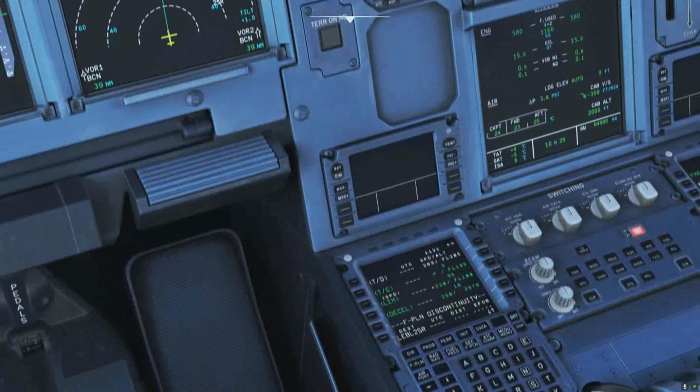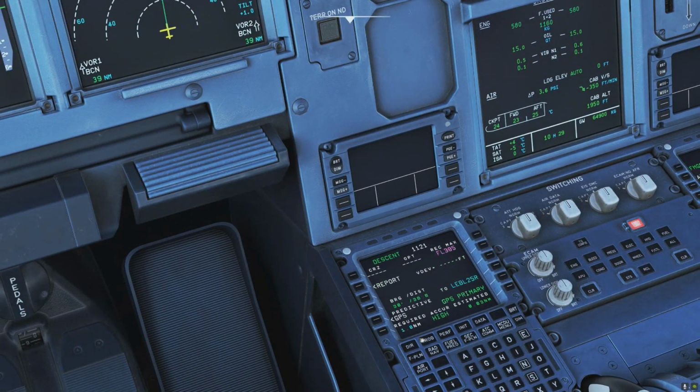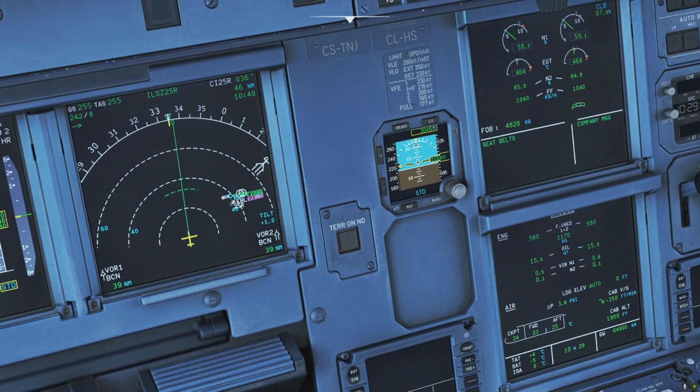And in terms of distance, if you look here, this distance now makes no sense whatsoever, because it tells us we are 38 miles away from the runway, but this is measuring from the aircraft directly to the threshold. This is not what we'll be flying. So in terms of distance, what you can calculate is that you're going to be flying 10 miles outbound and 10 miles back inbound. That is usually what happens. Those two rules together can help you to create a better picture.